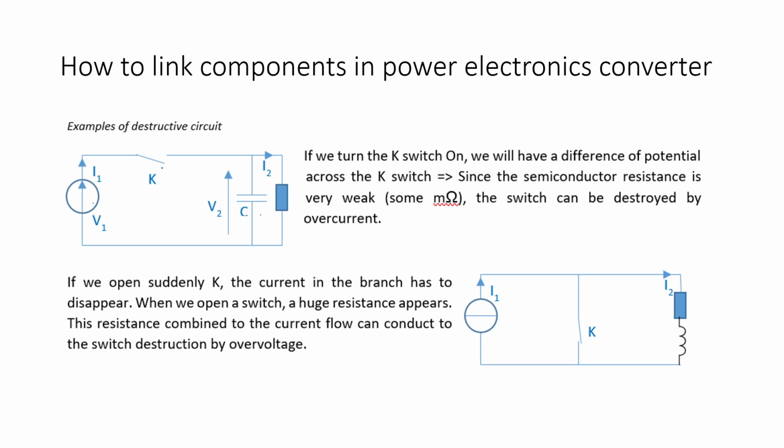When you switch on, what happens? At the initial state, the capacitor behaves like a zero resistance component, right? Because it has no charge. So when you give the current source in parallel, when you connect, it allows current to flow as much as the source can provide at the initial stage. So it's going to burn your capacitor.